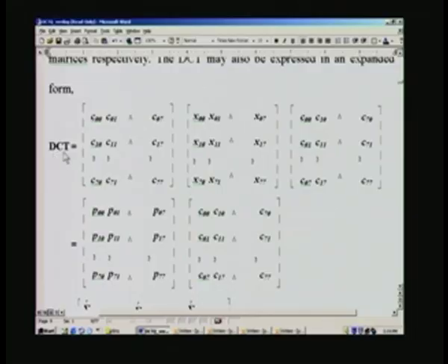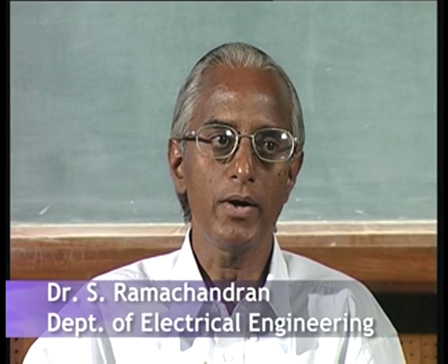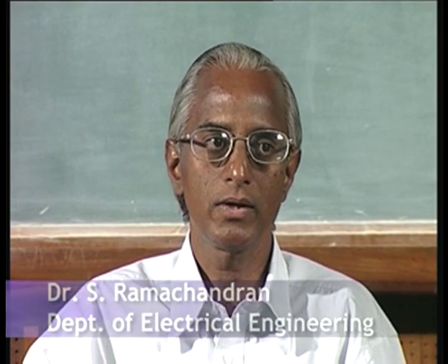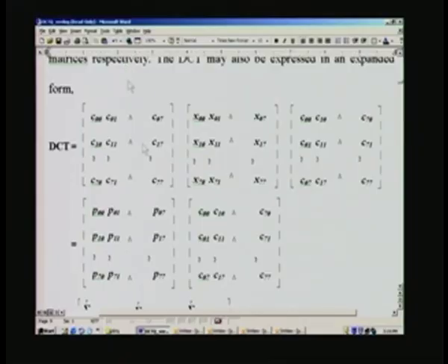The error arises by applying DCT followed by quantization, then IQ, IDCT, which gives the reconstructed image. So, you extract the mean square of the error arising through all this. If you plot mean square error versus block size, say 4 by 4, 8 by 8, 16 by 16, you will see that it has a least mean square. I think it goes something like that.